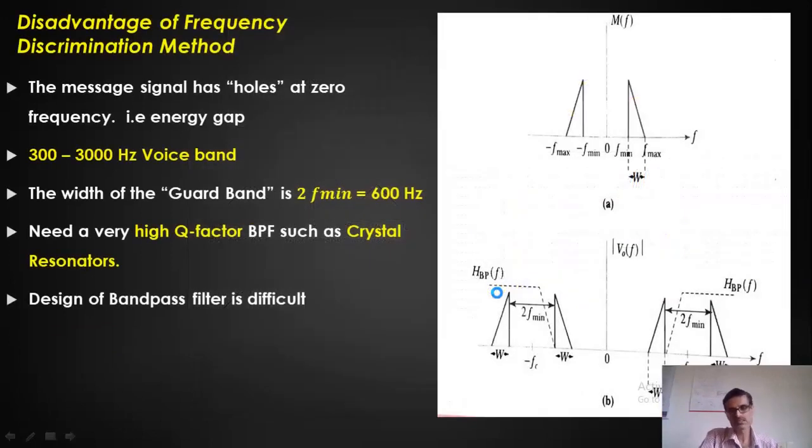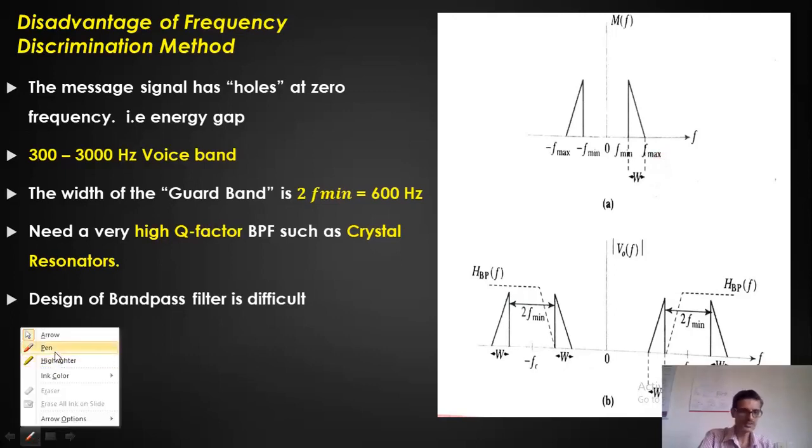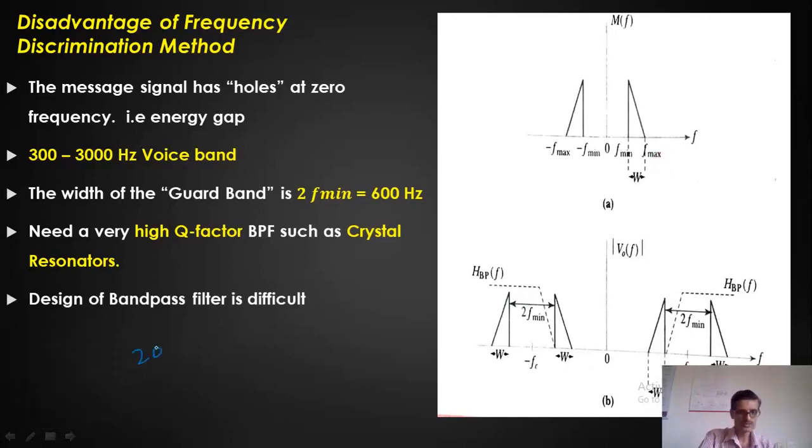Now we will understand this concept another way. In this case, what I have considered is my speech signal, or say the message signal m(t), extending between some low frequency f minimum up to a frequency of f max. For example, let us take an audio band. The audio band range is 20 Hz to 20 kHz, right? It is not zero. Practically, we usually consider it as zero to say highest frequency of W Hertz, but here this 20 Hz to 20 kHz is the actual audio band.